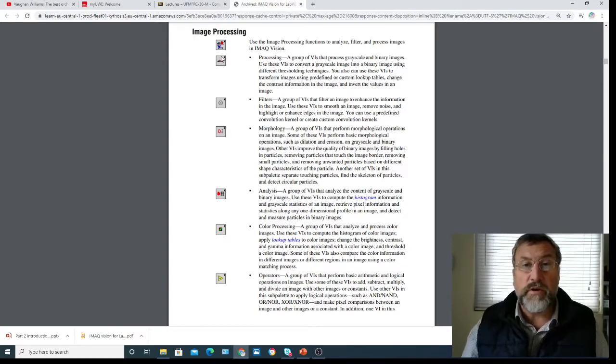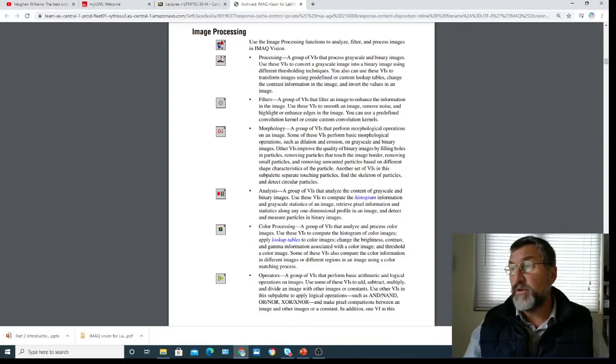Especially something I asked you about in the assignment is how you would deal with various problems that you might be experiencing, like changes in background light, vibration, temperature changes, even things like dirt, and it's quite common, dirt and muck kicking around in the factory environment. We've got a project on in Gloucester with a company, and we're working in a warehouse, and it's not exactly a clean environment in there.